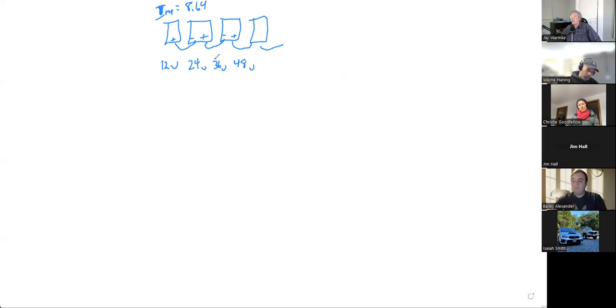So these were our choices. And as a matter of course, the 36 volt was kind of not used. So you were either 12, 24, or 48. So those were your choices. So as a result, most people just centered on 48 volt systems. That was the normal standalone system. It still is in some of the inverter specifications, things of that nature.